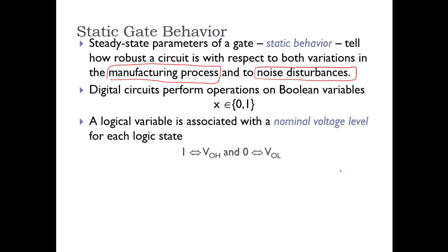So the silicon may not be of the same quality. It is possible that on the same wafer, the wafer I have shown you previously, maybe in the center of the wafer you have chips that are very well manufactured, and maybe at the boundaries of the wafer you have chips where the silicon is not of that quality.